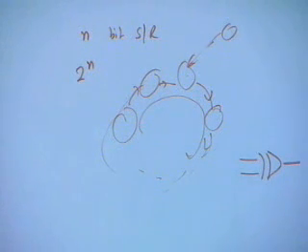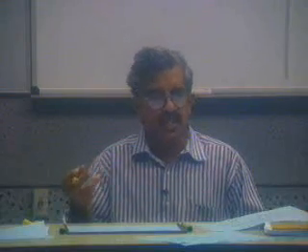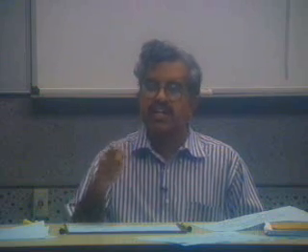If you look at either the AND gate, OR gate, NOR gate, NAND gate, any one of them, the outputs are lopsided. For 3 of the inputs, the output is the same. Whereas if you take an exclusive OR, if you consider the inputs are uniformly distributed between 0 and 1, the output is also going to be uniformly distributed between 0 and 1. So that's one reason that exclusive OR is the gate that is used.